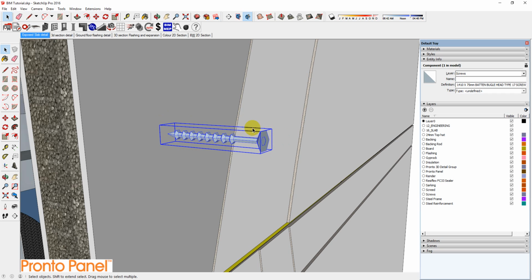So I modeled it in SketchUp, and then I used our BIM tool, and in that I was able to assign it to a layer, give it a name and definition, and as you'll see shortly, you can also put other notes as well as purchase information. When you BIM an object, it also means that Plusspec can capture it in the bill of quantities, so that you know, for example, if you've got 50 of these screws, it will automatically understand that you have 50 of them. Therefore, they've been quantified.